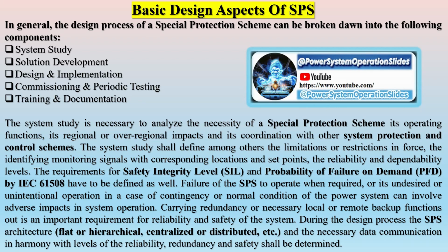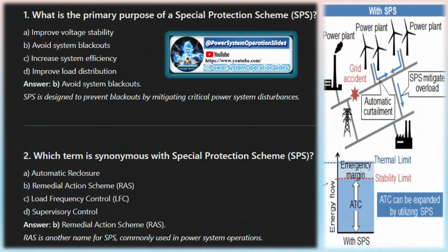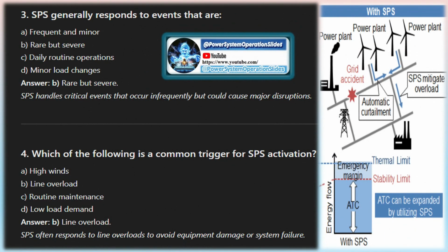Alert state. If the system parameters are still within admissible ranges but the system does not anymore meet the criteria given for a secure state, i.e. it is no longer N-1 secure, the system is considered to be in an alert state or endangered state. Typically, the system reaches this state after a N-1 contingency. This state requires application of remedial actions without any delay in order to come back to the secure state, i.e. to comply with the N-1 rule.